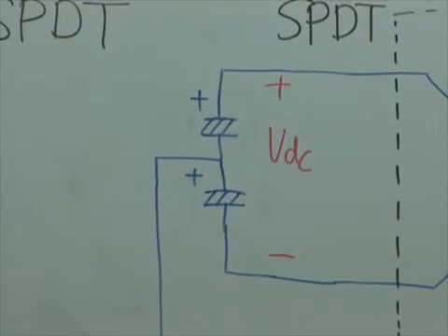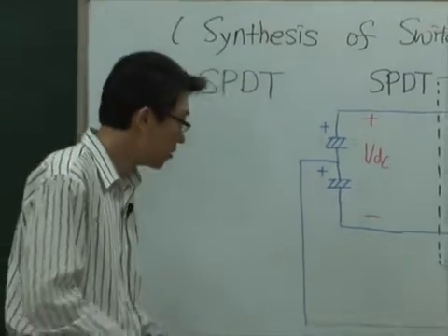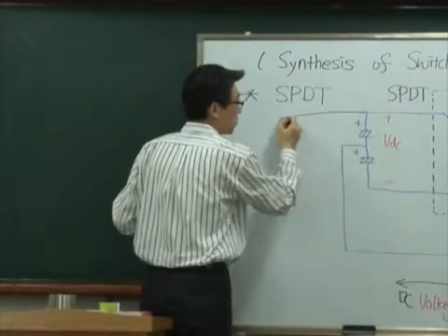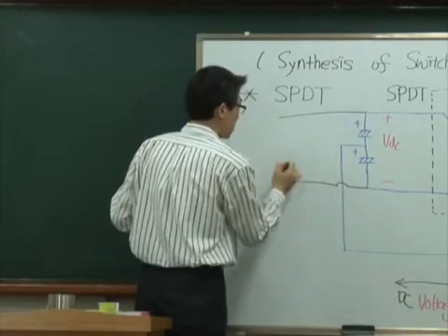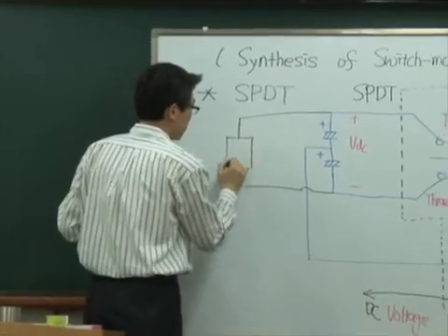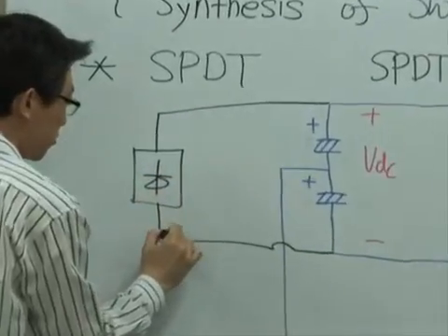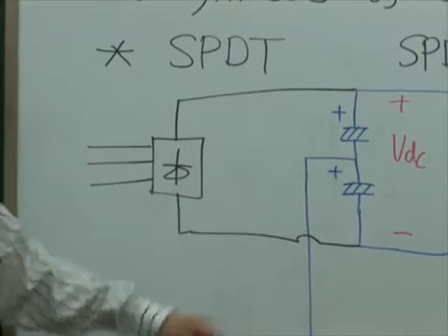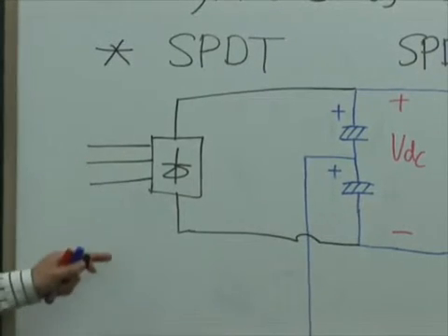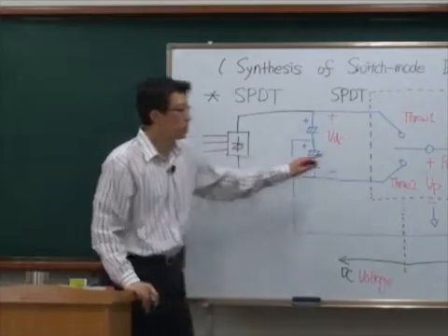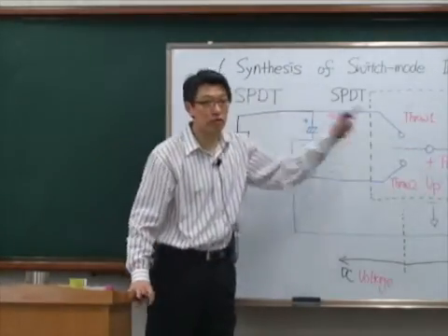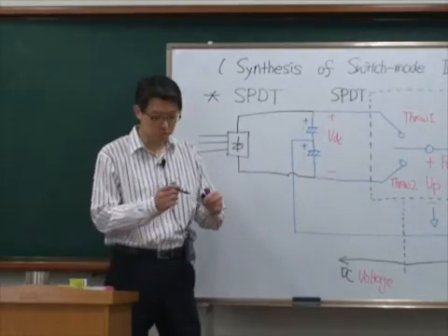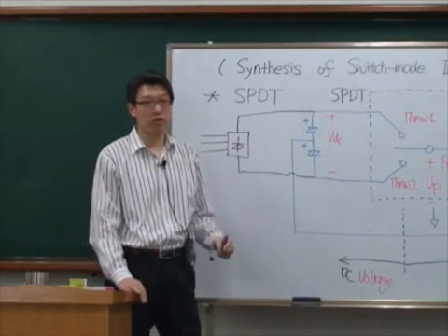Okay? And of course, now we can add here Diode Rectifier or Switch-mode Converter. Okay? Now this is one simple structure of motor drive system for single phase. Now this is single phase. If we consider three phase, now we have to have three single pole double throw switches, but that I will explain later. Okay?